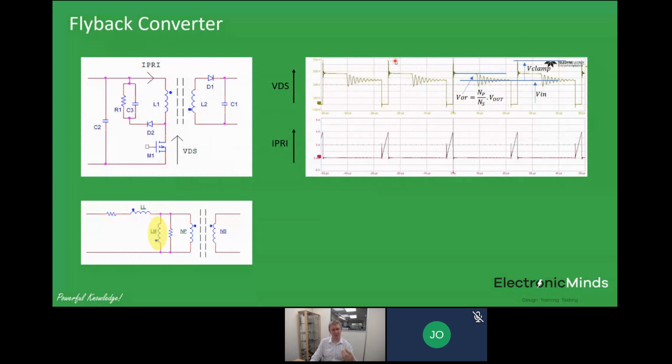It also gives you a feeling for why the flyback converter is only good at fairly low power levels, because it's quite hard to get the leakage to be very, very low. If you look at most flyback transformer designs, you're doing well if you get the leakage inductance to be about 1 to 2% of the magnetizing inductance. So unless you use an active scheme, you have to burn that power. So it causes an efficiency problem.